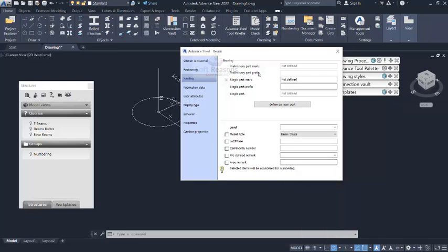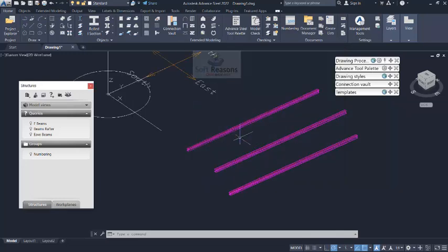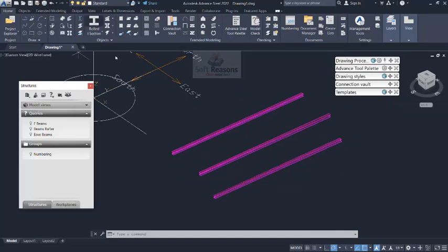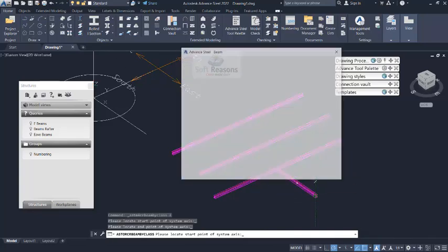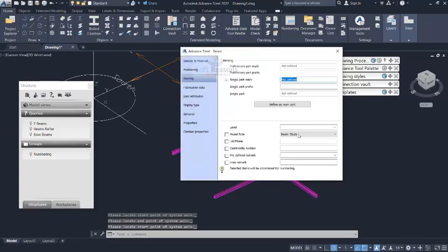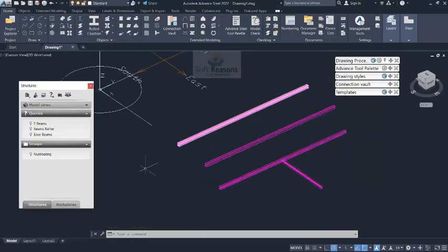So get that selected. I will right click and then activate model row, which means the next beam I'm going to draw is going to carry this model row. I click on close right there. This has been assigned successfully. I will click on that again, and then I'll pick this point and have another beam with the same model row. I enter. If you check back at the naming, you see it's beam stored right there. So now you have this beam.